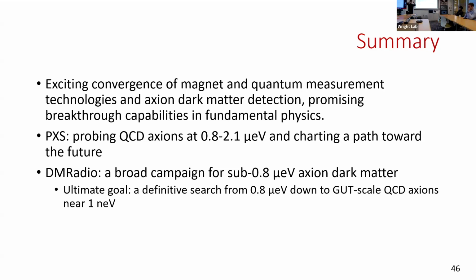So basically the thermal flow coming down cancels the joule heat going up. So the snake aspect ratio, the cross section is 4 millimeter by 25.4 millimeter, and it's about 85 centimeters long. That's what determines that A over L, doing that optimization.